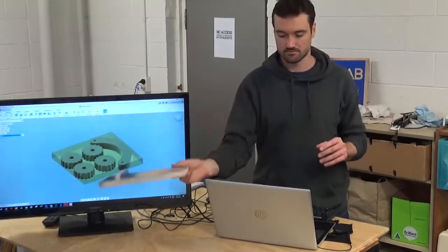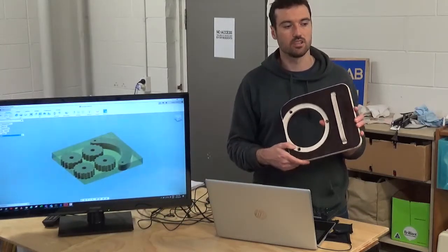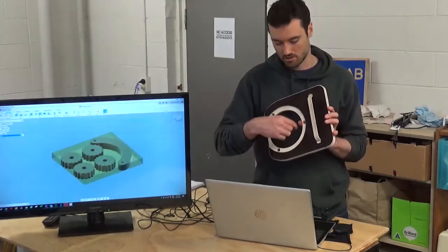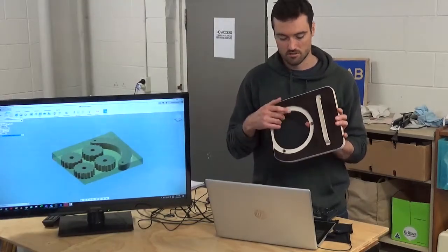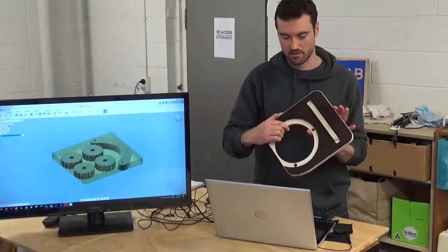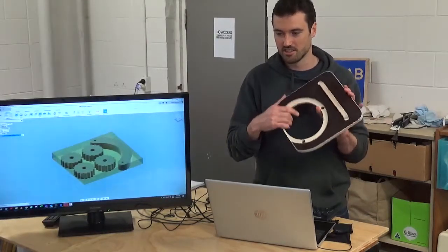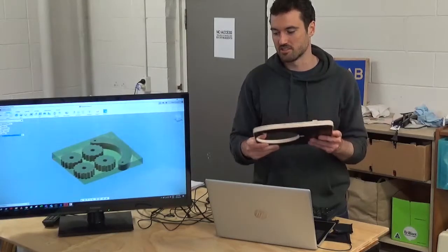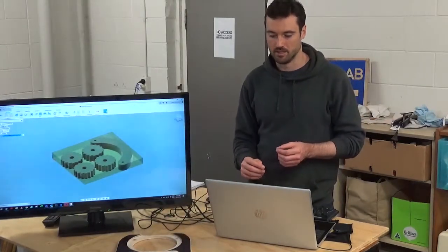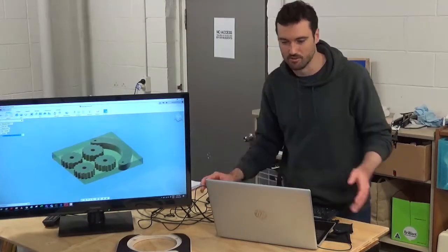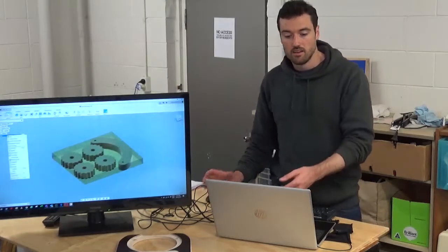And also your little bits in the middle, you want to do those first. When you cut out these guys, they want to pop out. So if you've cut out the outside, this whole thing can rotate, and then you've lost your positioning. So basically, you're going from most likely to move to least likely to move, or fall out of position.